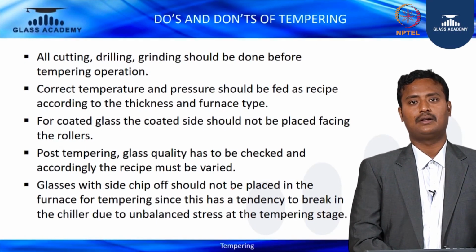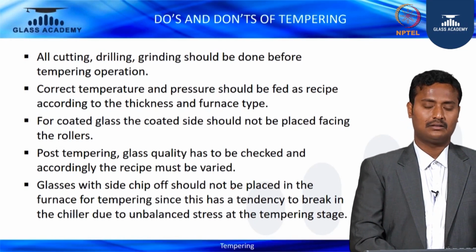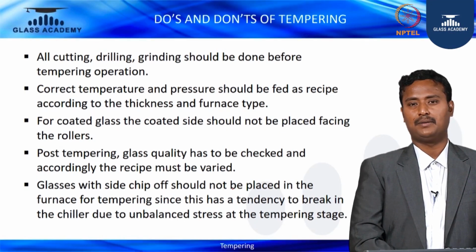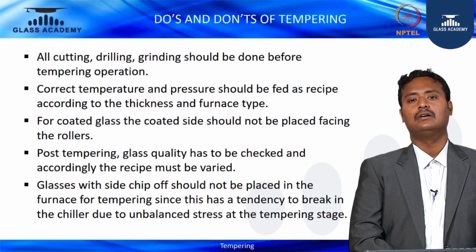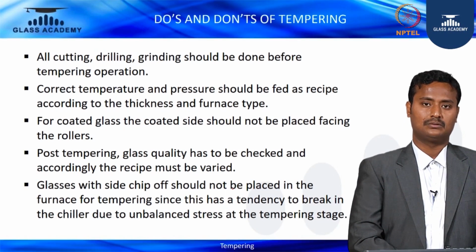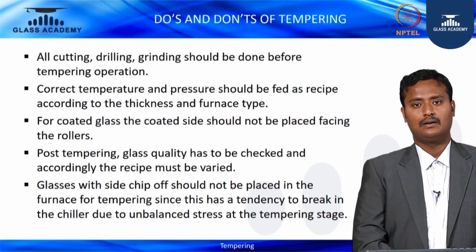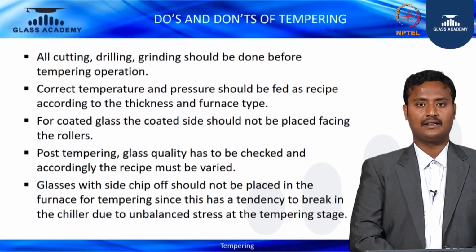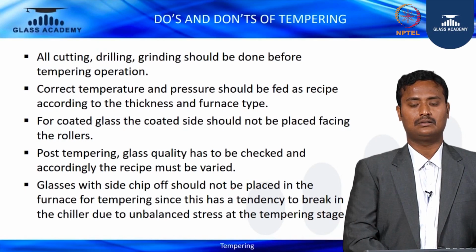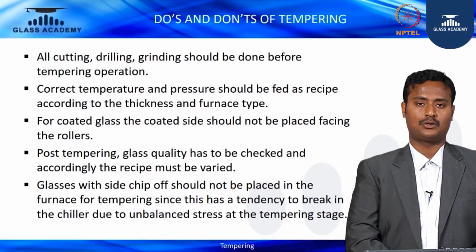Post tempering, glass quality has to be checked according to the recipe, and you can check the quality in terms of tempering parameters. If anything is obvious and not acceptable to the naked eye, we can eliminate it with the help of tempering parameters. Or else there is the European standard EN 12150, which helps us set the quality we are expecting for particular projects.